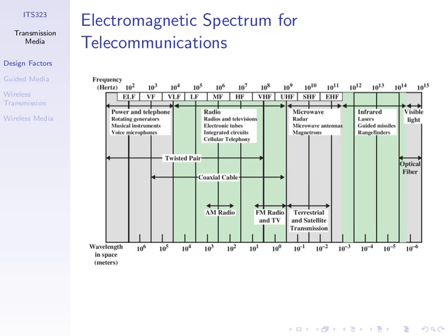So even though the line is longer, the bandwidth is less. Similar for optical fibre, we'll talk about what that is. It has a very high bandwidth available to use, 10 to the 4 up to 10 to the power of 5, which is much higher than those other systems in terms of bandwidth.